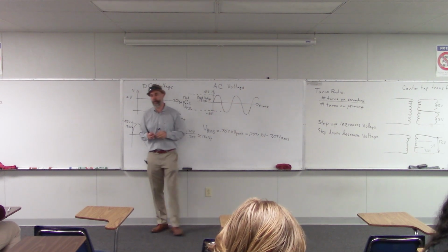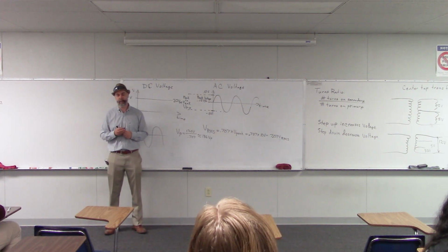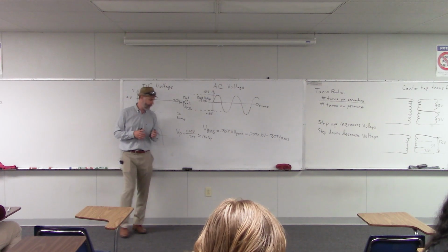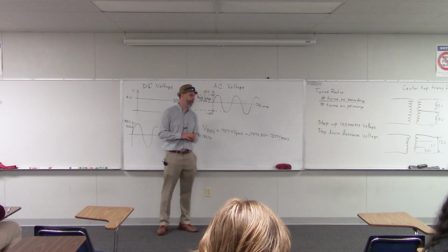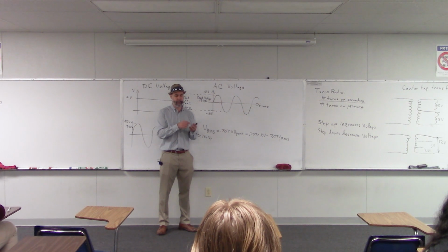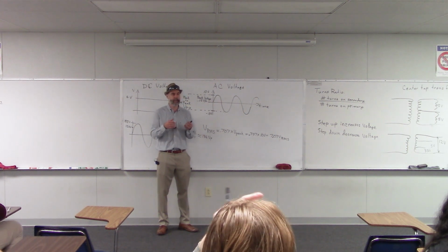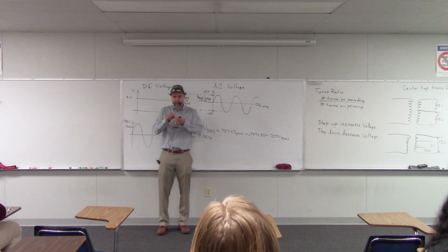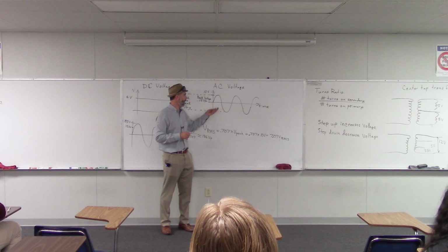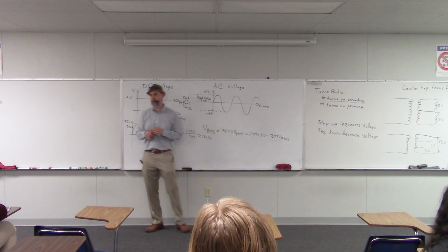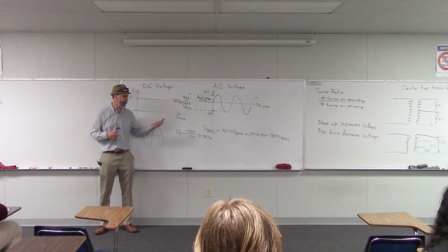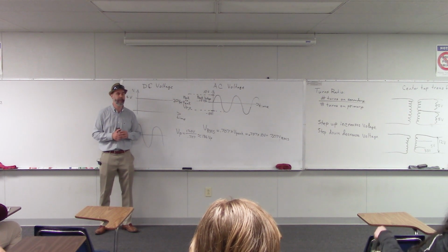In fact, if you look at fancy DMMs, they will say that they have a true RMS measurement, or true heat RMS, which means they actually have a little heater inside there. They're actually using that to calculate the RMS voltage from a signal. So yeah, it's still done. That is the comparison there.